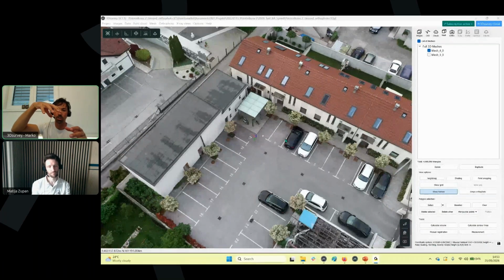So what you are going to do, fly with the drone a bit from the side, like camera angle, first 60 degrees, then 45 degrees, 30 degrees, and then add also photos with your phone camera or something like that. Even better, our advice is use drone camera, hold your drone in the hand and trigger cameras, because drone camera it's much better, much more powerful if you compare to phone camera.